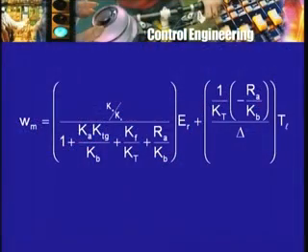But as I told you, you should go back to our original design data and work out some numbers so that one gets some idea of what's going on. What about the set point changes? As the expression shows, omega m is directly dependent on ER. So if you want to increase the speed at which the motor is to run, increase ER to a suitable value. If you want it to decrease, decrease ER to a suitable value.